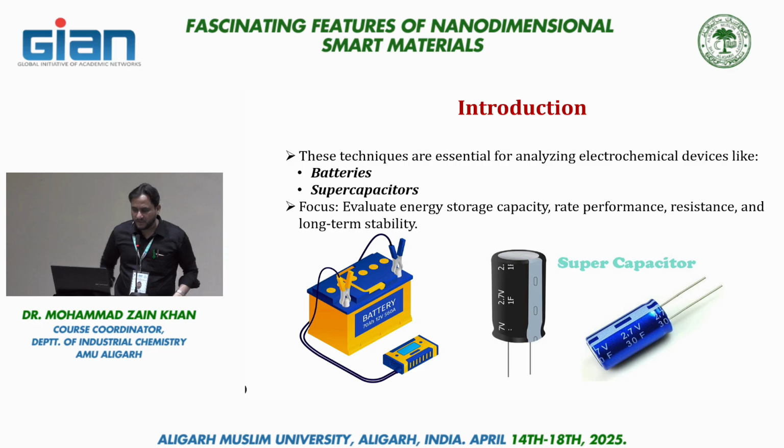As I was saying from the start, the two energy storage devices are the batteries and the supercapacitors. The major difference in terms of application is that a supercapacitor provides a surge of charge, a surge of power at one point. It gives very quick delivery of power, while a battery provides gradual power, although for a long duration of time. This difference is because of their mechanism.